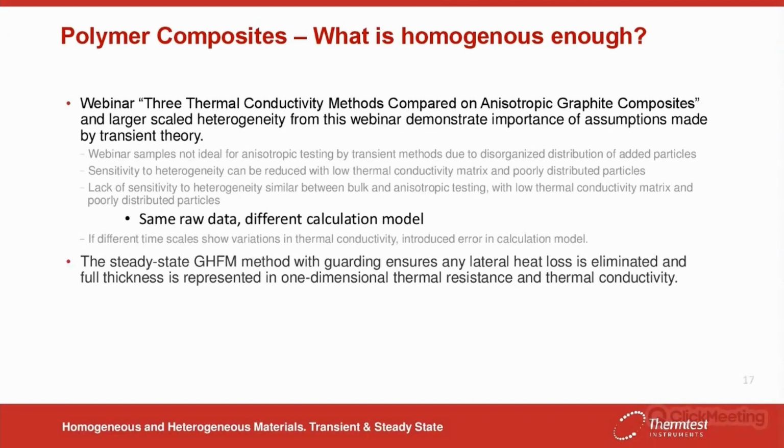That was a bit of an aha moment: depending on the thermal conductivity of your matrix and what you're introducing to it, if it's too far away from one of the surfaces, you might not see it at all. You might not even see the effects of reflection from that higher conductivity particle in your transient residual, just due to the lower conductivity matrix not diffusing that back to the residual.